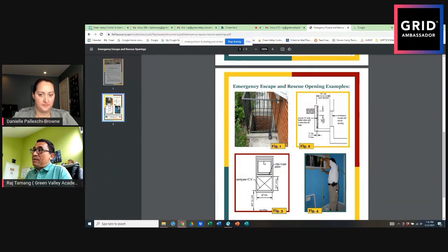You have to remember, when I have a double hung window, double hung means the upper sash and lower sash. The lower sash you can move up, right? You slide up. That means even if my window is 5 foot tall, the actual opening is only halfway, because the panel is still there.